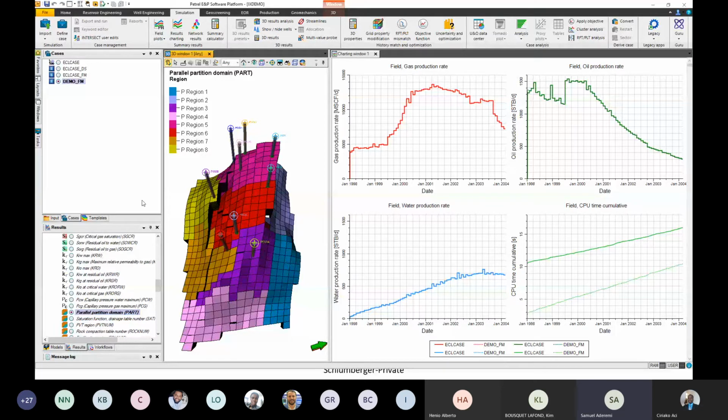I hope that helps. That is super interesting. Thank you very much. That clearly answers the question. You said about 50,000 cells per processor. That's your rule of thumb that you're suggesting? Yeah, as a rule of thumb, if you go below that, you probably don't get much scalability value. Okay, excellent. Thank you very much for that. You're welcome.